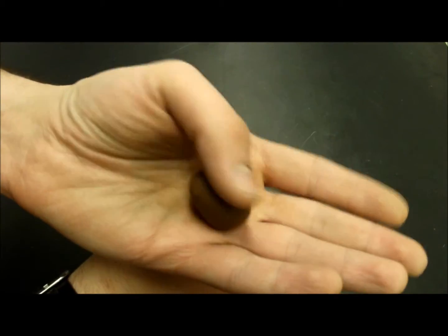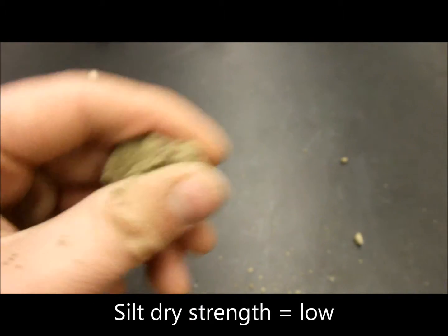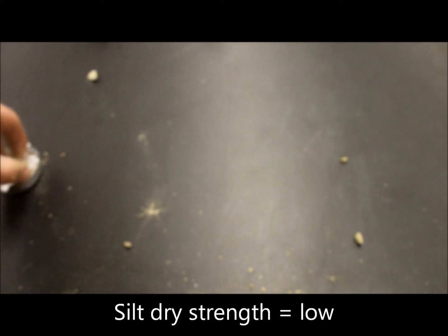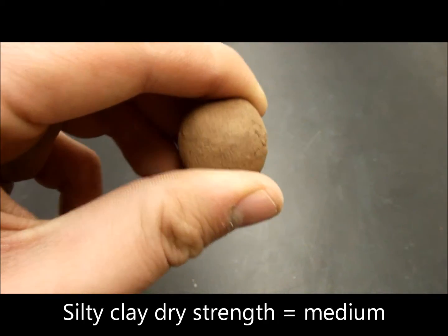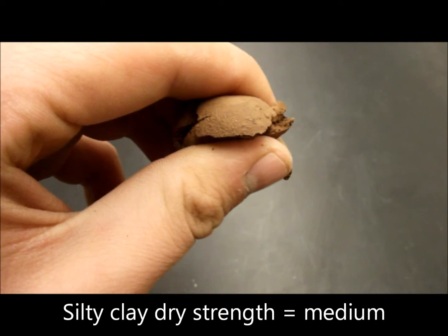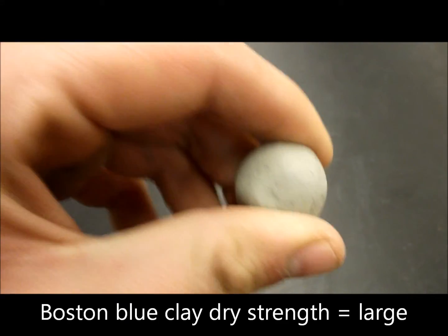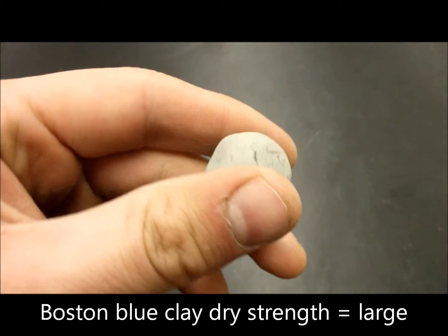Dry strength. We test for dry strength by watching how a dry soil crumbles under pressure. For this test, take a soil specimen approximately enough to make a 1-inch diameter ball, adding enough water to make it moldable. Once the balls have been dried, test their dry strength by crushing them between your fingers, taking note of the pressure required to crush the sample.